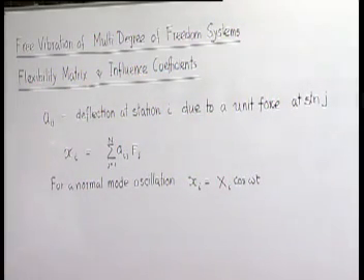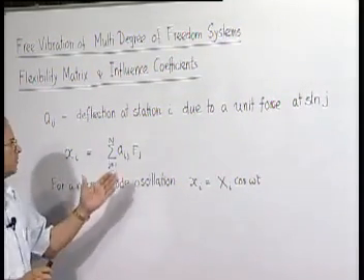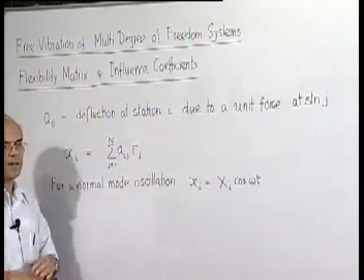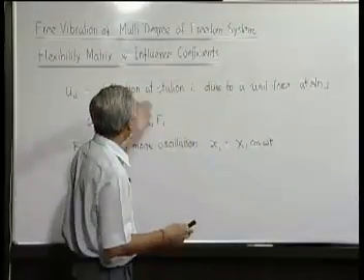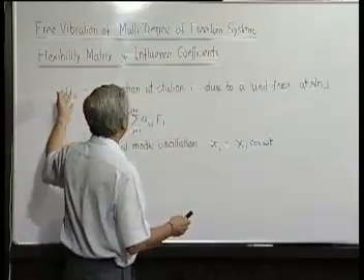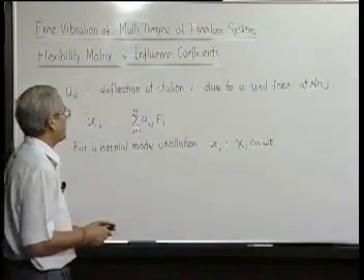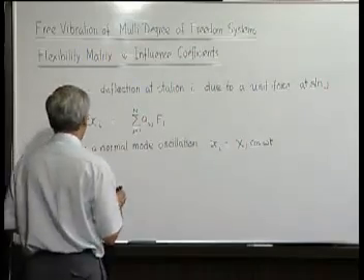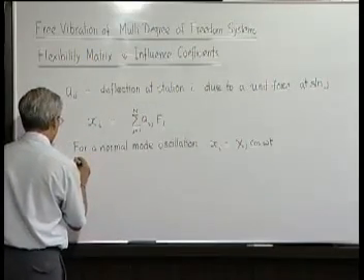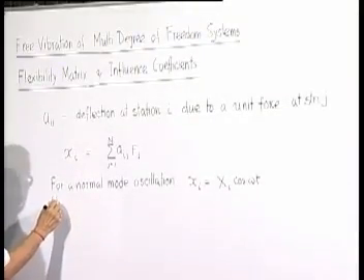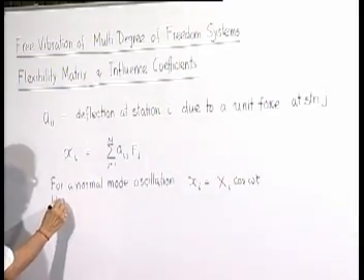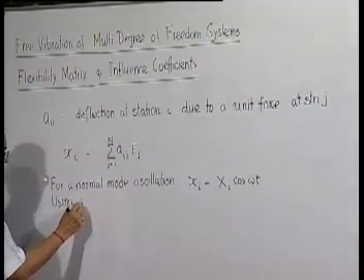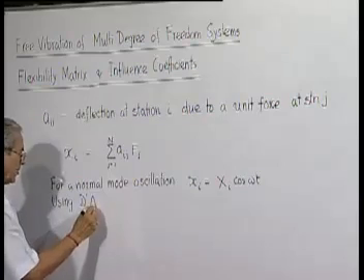Now, the question is that when such a vibration takes place, what will be the forces acting? How do you convert it? As a static problem, it is very simple, but a dynamic problem we have to convert to a static problem by applying D'Alembert's law or D'Alembert's principle. That we have done earlier also.